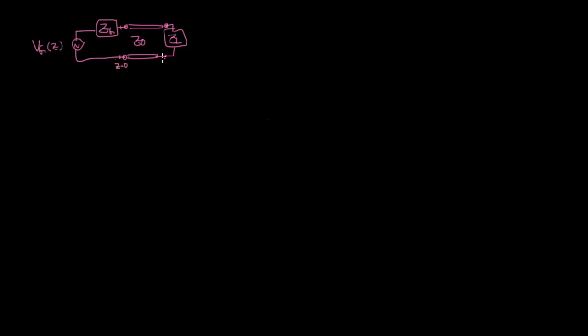One of the main things that we've also started introducing with some of our calculations: before, we set z equal to 0 on the generator end and z equals L on the load end. For these calculations, since we're using input impedance and all that, we're going to also use the coordinate system where we set the origin to be at the load end. That will make our calculations and our formulas congruent with what we were talking about before.